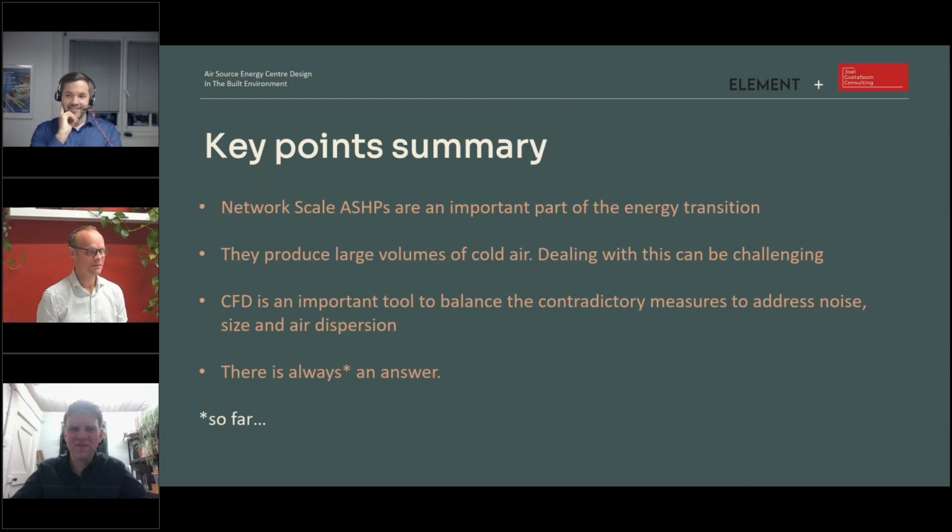Okay. So coming back, the example I showed in Denmark had all manner of different heat sources. One of which was an 11,000 volt electric boiler, which is a heat battery, with a big thermal storage in water in that instance. That's there to take up the excess electrical energy made by Danish wind farms. So the economics are all dictated by the electricity pricing, which is dictated by the electricity sources. With heat pumps, they will always use less electricity for the same outcome. They don't take electricity and turn it to heat. They use electricity to take heat from somewhere useless and make it useful. They pump heat. That clues in the name.